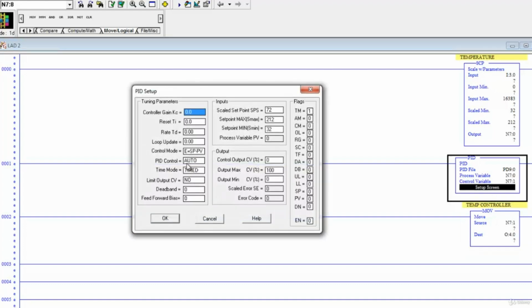So when this program is loaded onto a system, and this is not a process that can be done any time before you're actually up and running on the live system, caution is recommended. You want to be aware that if you change a variable too drastically, you can cause a process to become unstable and you could potentially damage equipment or kill somebody. Take this process, do it slowly, and if you have never done it before, please don't experiment on anything that can cause a hydrogen explosion or release toxic gas or anything to that effect.